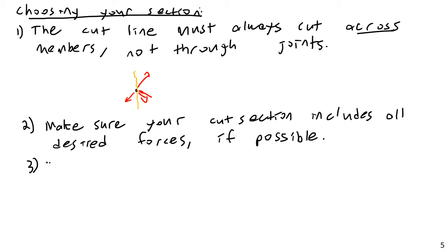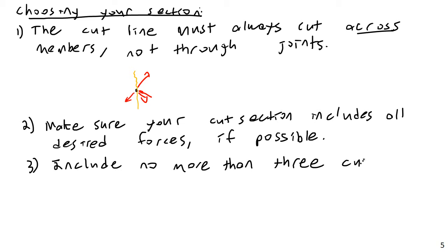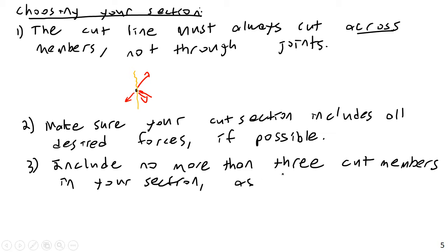And 3, make sure to include no more than 3 cut members in your section, as each cut member reveals another unknown force.